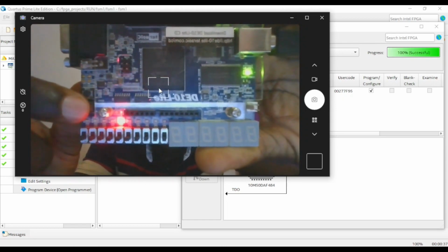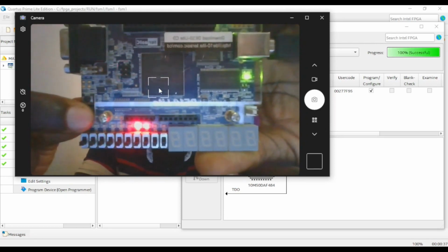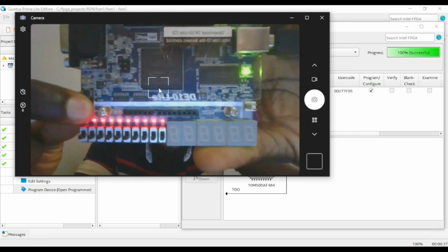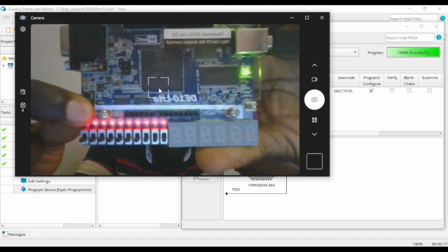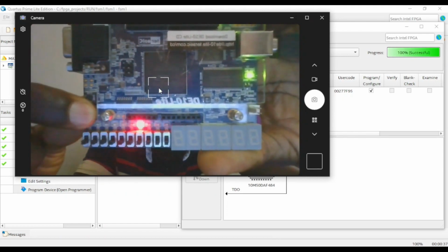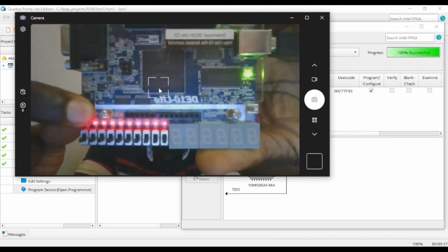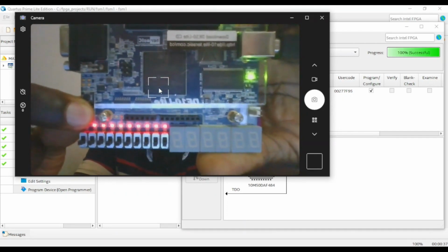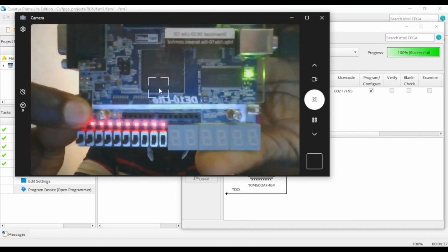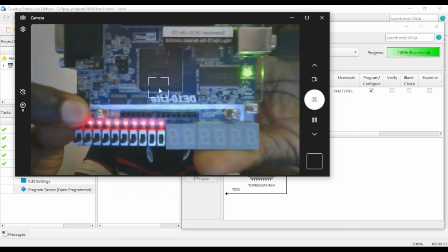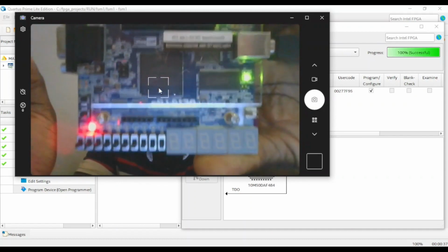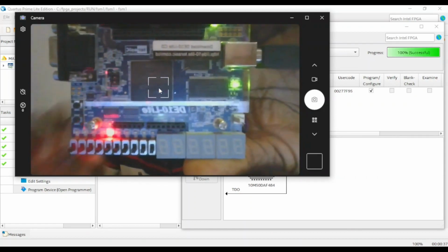And to give you a hint as to why that is, if I hold down the button now, you see that it is just transiting from state to state, the way it looked earlier on. That's the problem I alluded to earlier on that we will definitely have. So we are not to check when button is 1 or when button is 0. Rather, we're supposed to check rising edge or falling edge. That is what will work.